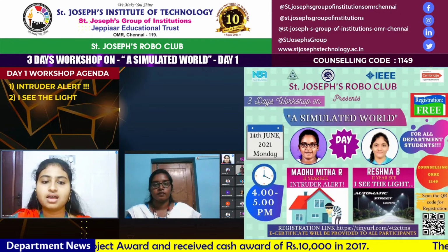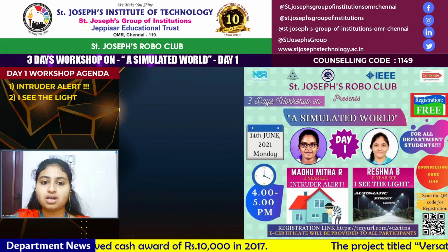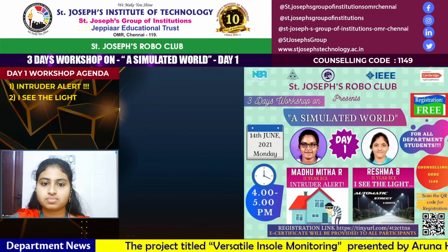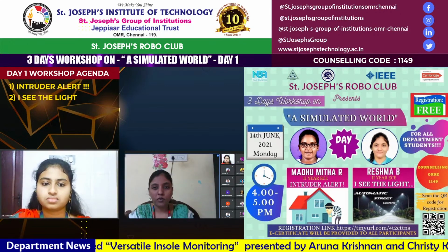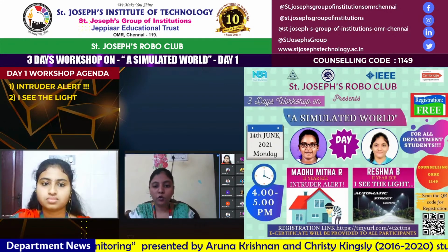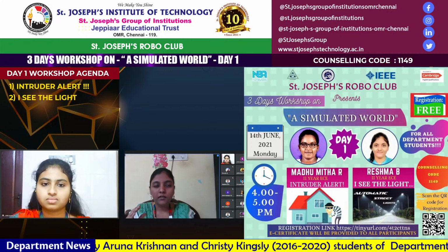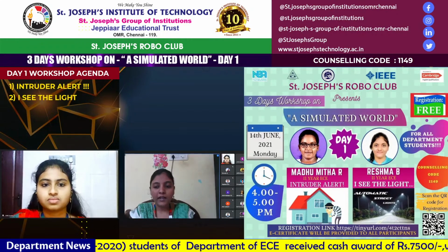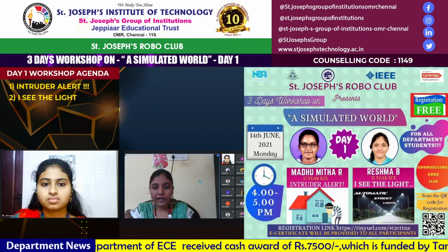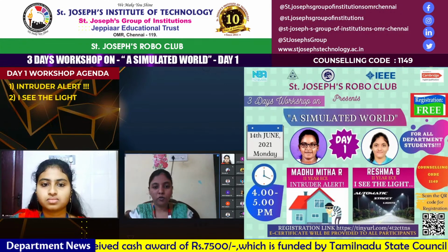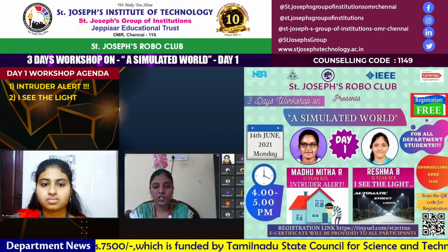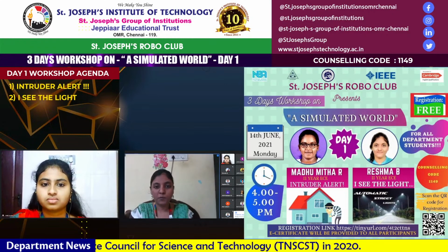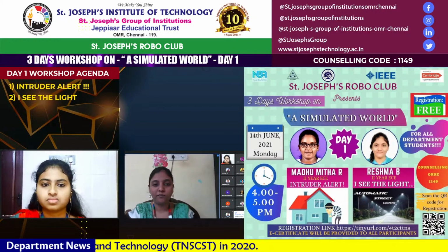Okay, thank you, Madhumita. And the next questions are for Ms. Reshma. First question for you is, why do we use resistors in the circuit? Now, the reason why we use resistors in the circuit is that the LED can only withstand certain values of current. That is, it can only withstand current up till like 0.20 amperes. We don't want the entire current to pass through. We need to regulate it and make sure that the LED doesn't get short circuited or combusted. So that's where resistors come into play. They regulate the amount of current which passes through and make sure that the circuit works properly.